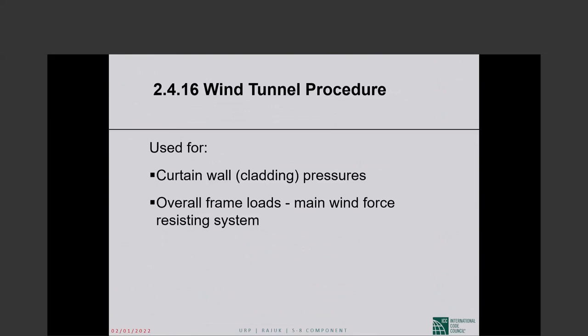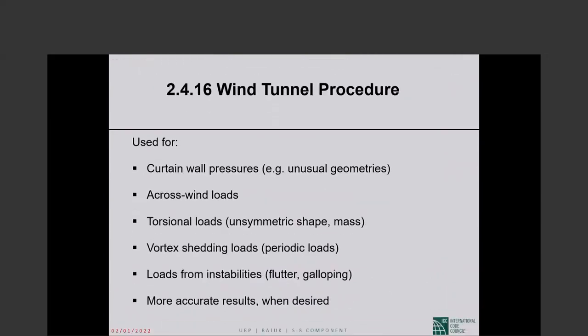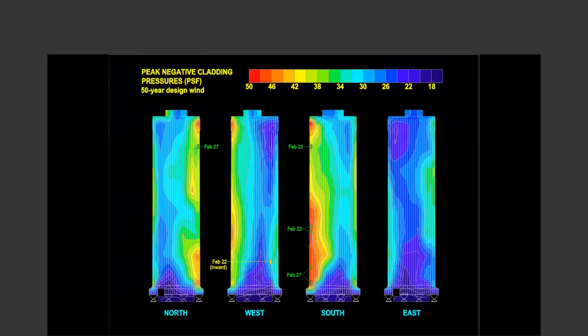The cladding loads, some of these things are probably a little bit repeated. Let me talk about cladding pressure because there is design of the cladding itself, and then there is design of the connection between the cladding and the structure, which is more important in many ways. And for both, you need the wind suction on the cladding.